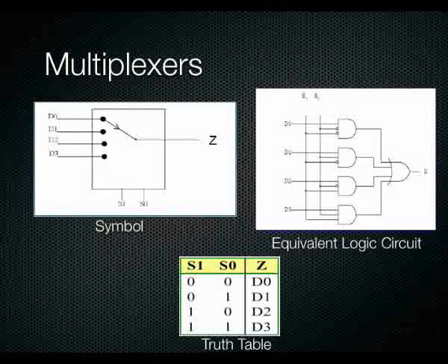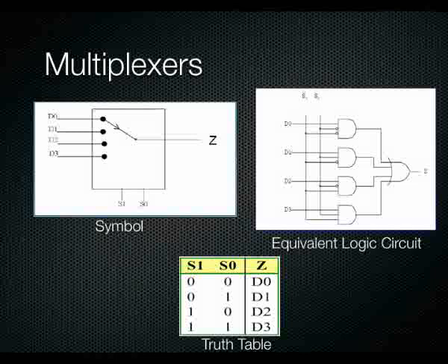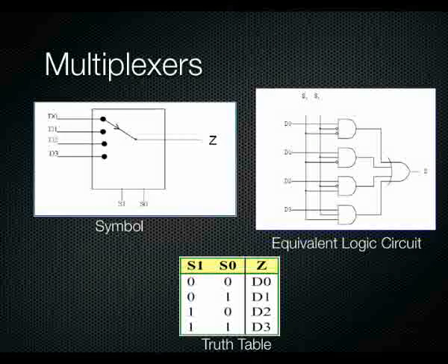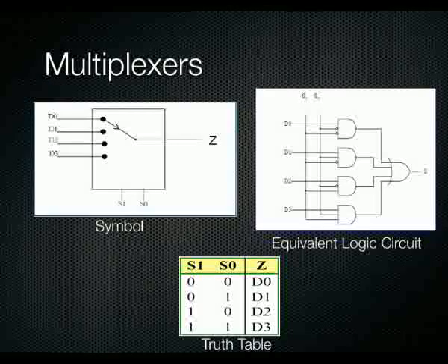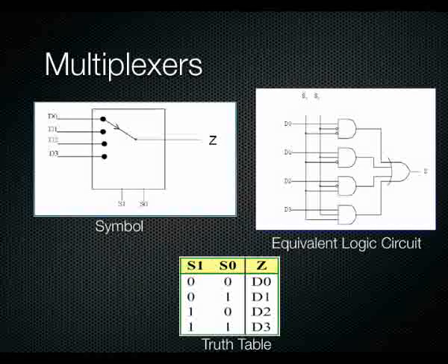So this is useful where you might have multiple devices and you've only got a limited number of I/O lines to connect to those various devices. Instead of having all those devices directly connected to your microprocessor, you might only have, say, 8 bits connected to a multiplexer, and then using that multiplexer you may connect various 8-bit devices at one point in time. So you can switch between a whole heap of different devices. You don't need to have enough I/O lines to support all the devices. You can simply run through a multiplexer and have it switch through those devices for you.